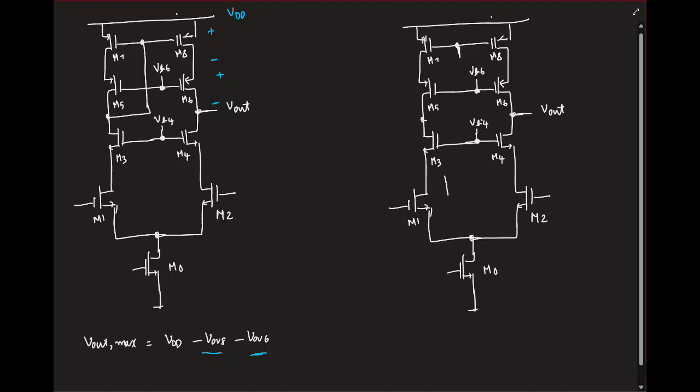We said we'll try to make sure the current flowing through the NMOS branch, I0 by 2, will be forced in this PMOS branch. So the current from M7 is buffered by M5. So we decided to compare the current here with the current in the NMOS, and that's why we made this.